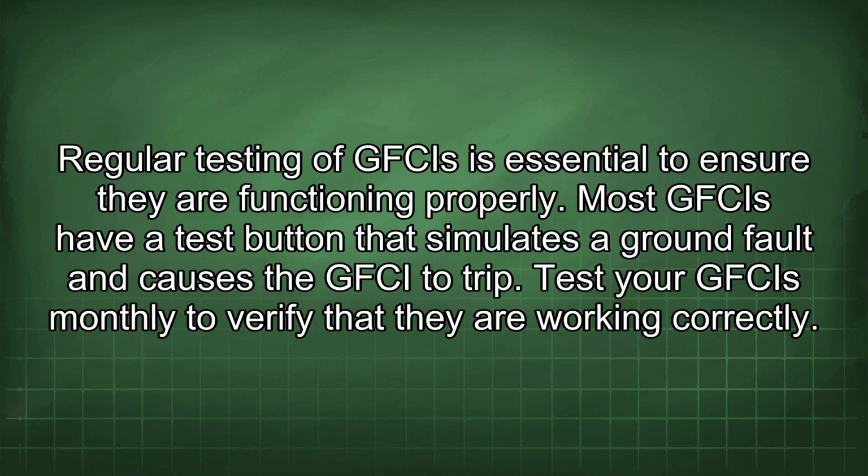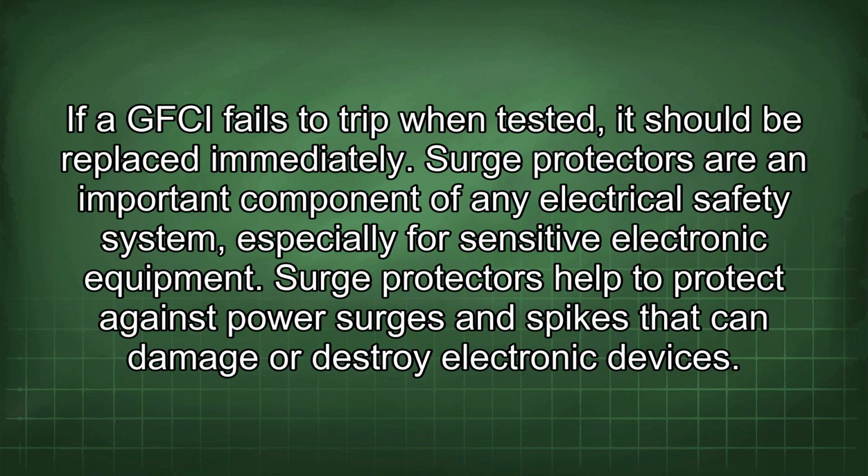Regular testing of GFCIs is essential to ensure they are functioning properly. Most GFCIs have a test button that simulates a ground fault and causes the GFCI to trip. Test your GFCIs monthly to verify that they are working correctly. If a GFCI fails to trip when tested, it should be replaced immediately.